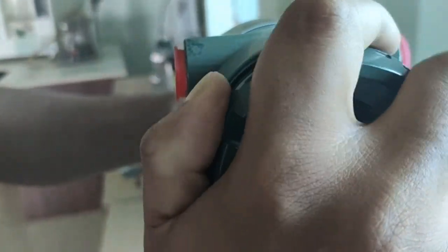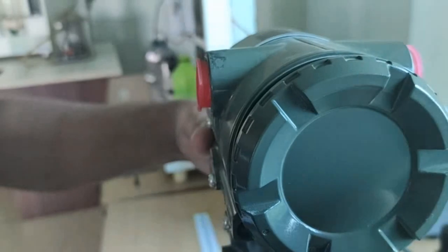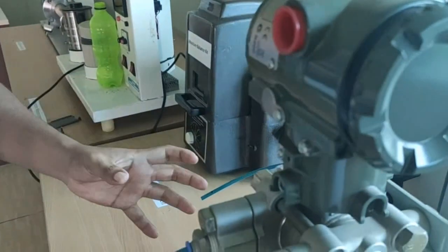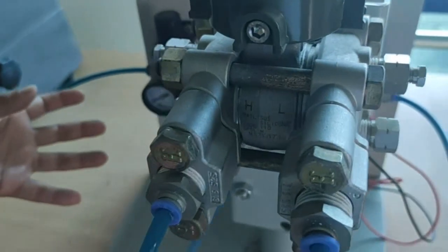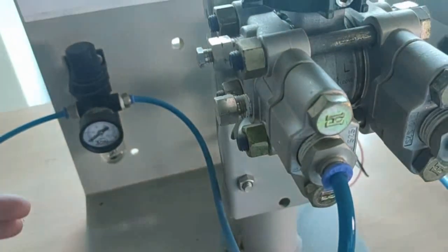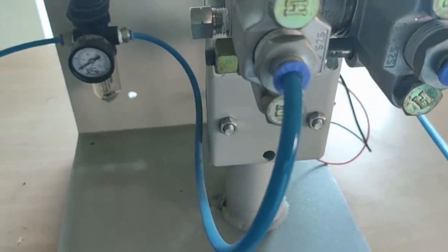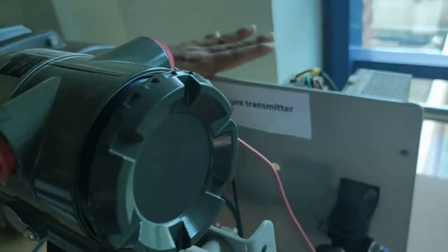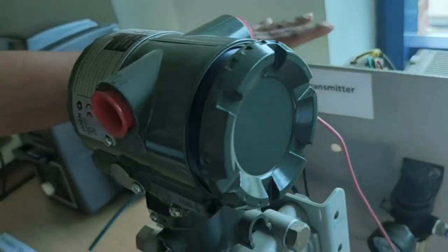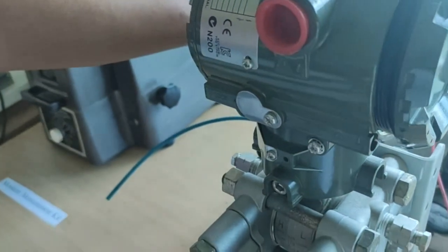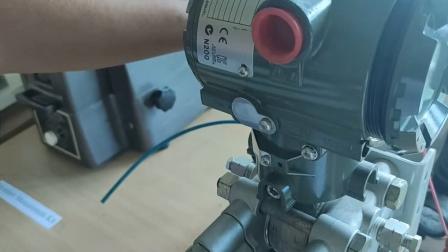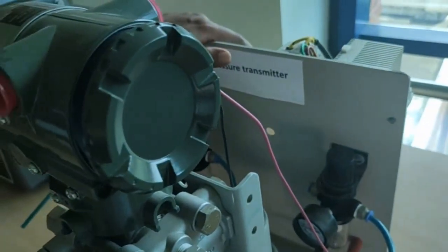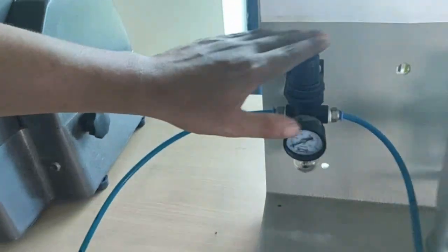It requires a supply of 24 volt DC basically, and in industrial applications, whenever we measure the pressure difference, it will be processed, conditioned and amplified, and we will get an electrical signal. For this purpose the measurement is done within the range of a 4 to 20 milliampere current signal, and in some applications 0 to 5 volt or 0 to 10 volts may also be used. So here you can see 2 points are there, these 2 points.